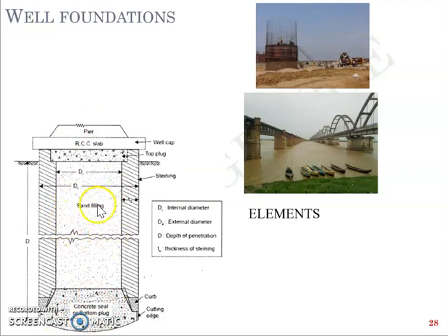Now, this cavity can either remain as such or can be filled with sand. You are left with the two options depending on the lateral load acting on the well foundation and whether you want to resist the lateral loads using the weight of the well. You'll have to fill it with sand.